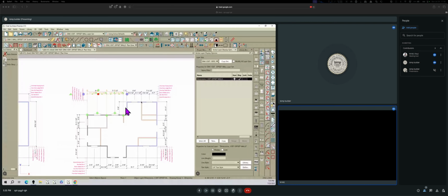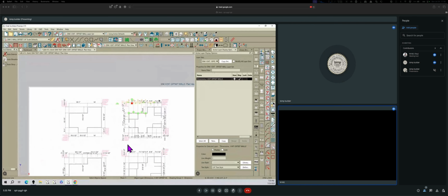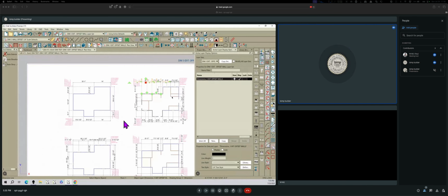Typically, I stack frame, so whichever is what we'd call the boss corner, boss wall, I'll hang past the length of that stud or that wall, and then I'll pull the first layout 15 1/4 to the layout, and then from there 16 inch on center.